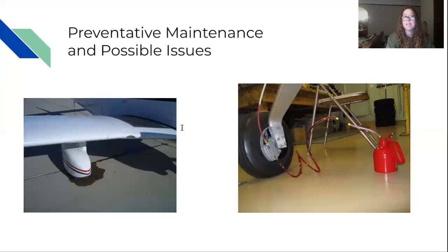So if the pump is making a lot of noise, this could mean you have cavitation, which means that there are low pressure bubbles because of how the pump is rotating. And this could be caused if the temperatures are too low, if there's dirt, if there's any problems with the tubing, or if the fluid is too thick. This will cause the pump to move slower than it should be moving.